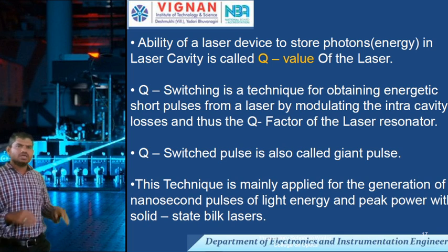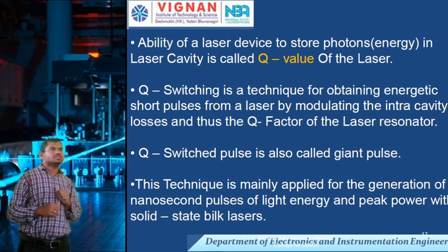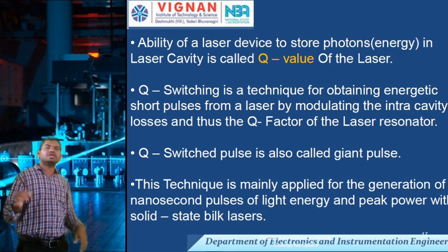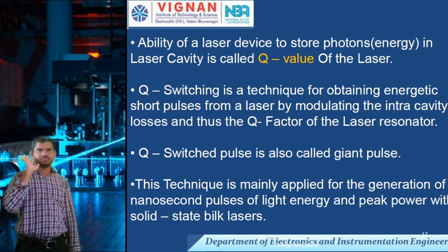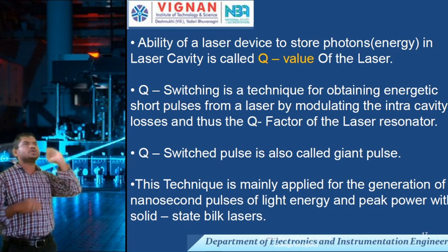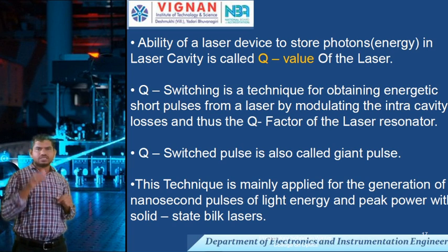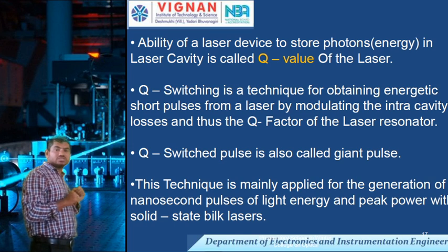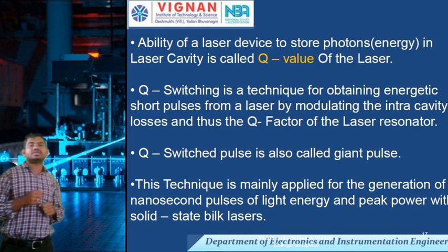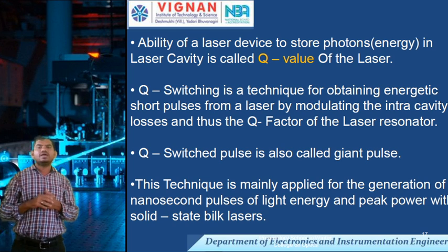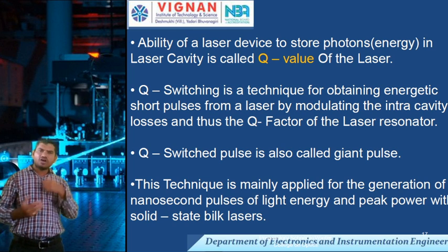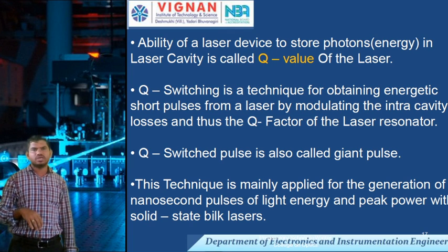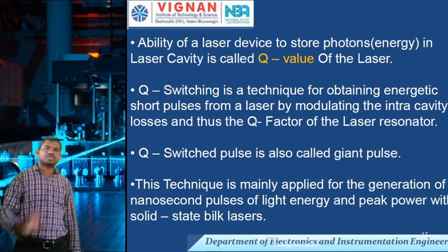What is the definition of Q switching? It is a technique for obtaining energetic short pulses from a laser by modulating the intracavity losses, and thus the Q factor of the laser resonator. After we get some laser output, we have to modulate that output in the Q switching technique.